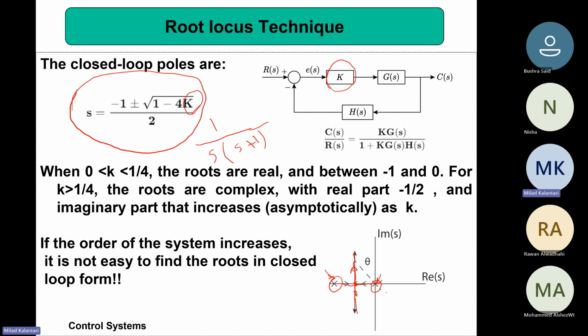If this is open loop, we know that the system is marginally stable because there is one pole at the origin. But once we increase the K, the poles come to this real region, and then they intersect and then they separate. When they are separating, we know that this is a second order system with some damping factors and some overshoots. I mean, we already have some sense of how the response is, right?